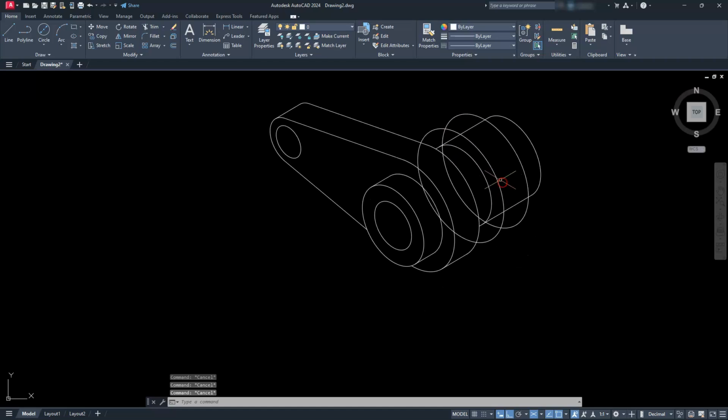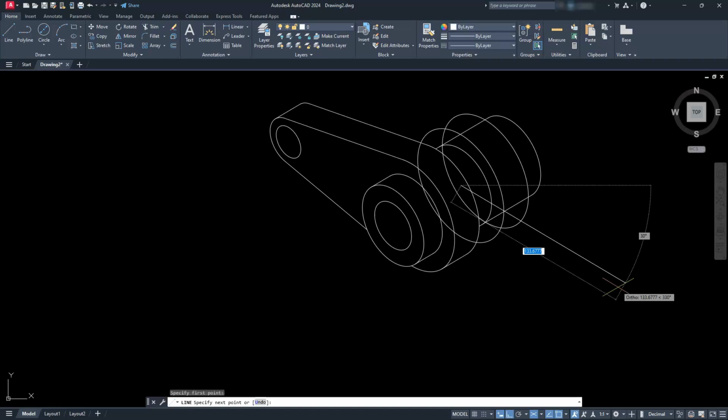Alright, so now I have this shape, kind of what's happening here. Now I can start already trimming out most of this, and we can see that we can get rid of some of this, right? But I'm going to wait till I get my lines that go across here to be able to fully trim this out. Let's go back to the line command. And then we're going to find the center of this one here, right? So you'll see which circle I'm selecting on. I see that center here, so I'll do a left click, come down this direction, and then the height of this, or the length in this case, should be 100.